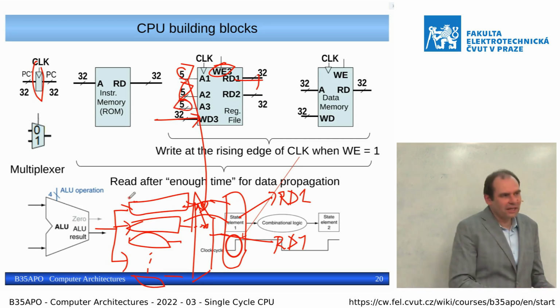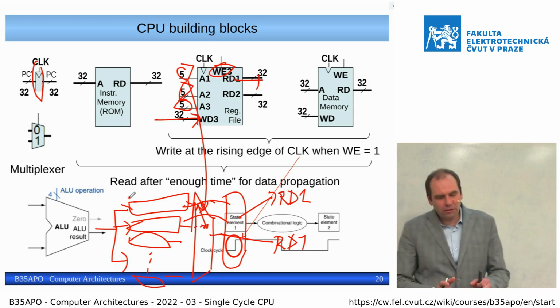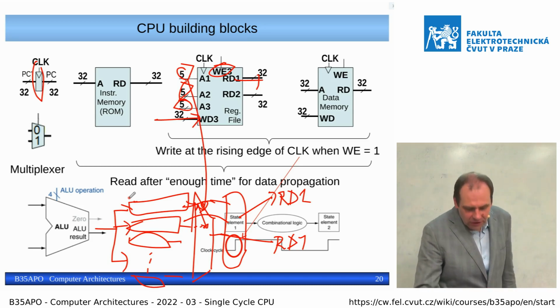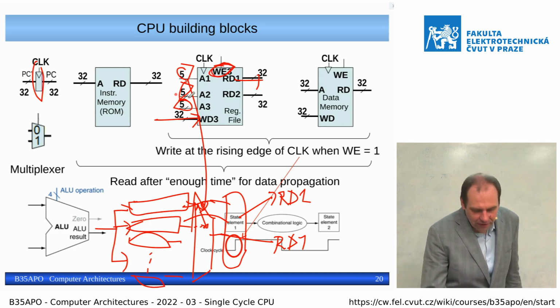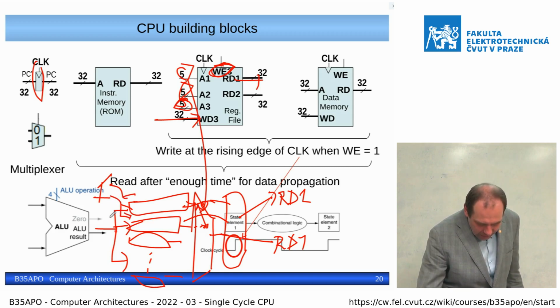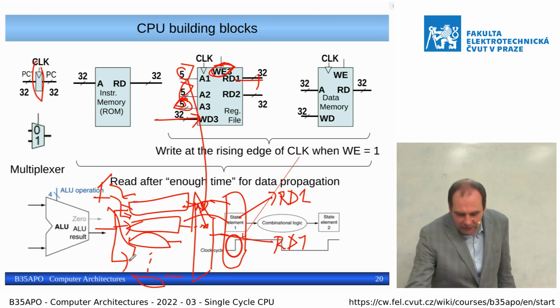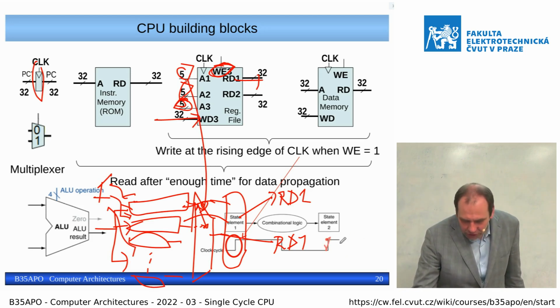So we take the 32-bit data, provide it on the input of all the registers, but only in the case that we enable the write and a register is addressed by some decoder. So basically there is some address decoder which has 1 line for each register and enables that the data should be written at the next clock edge.